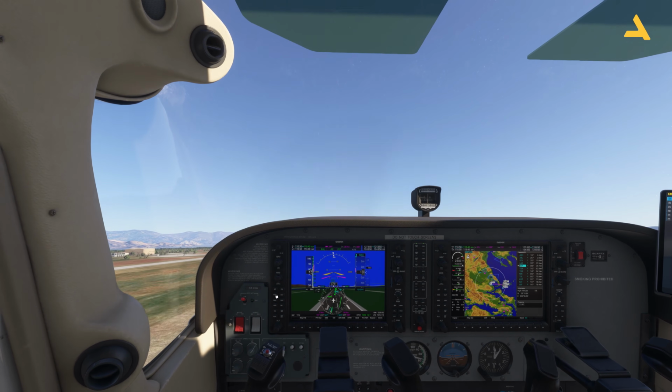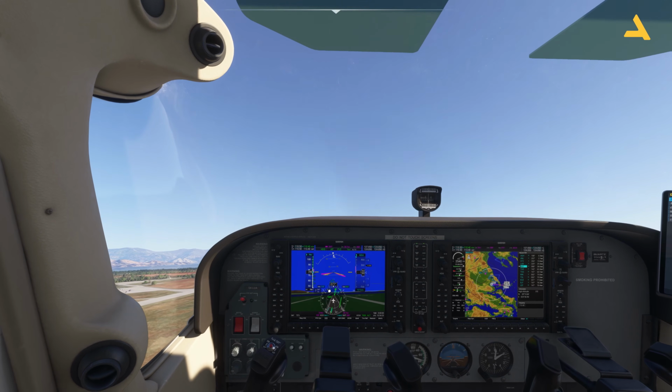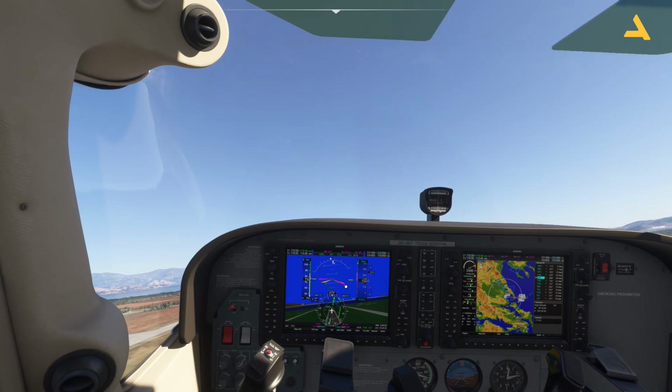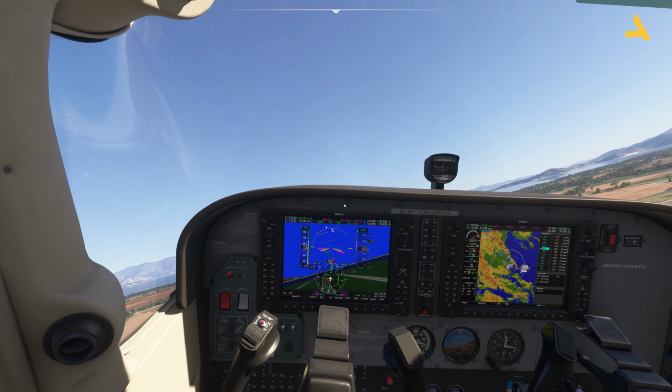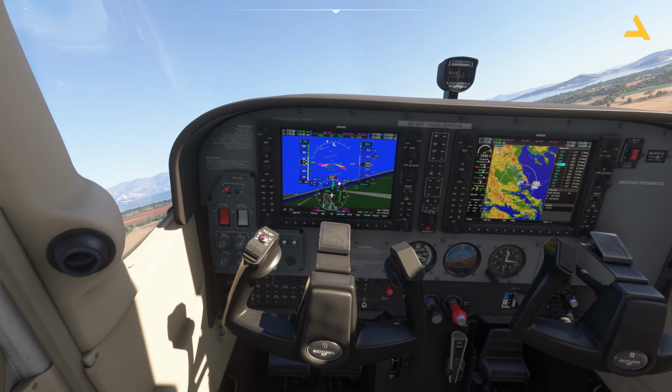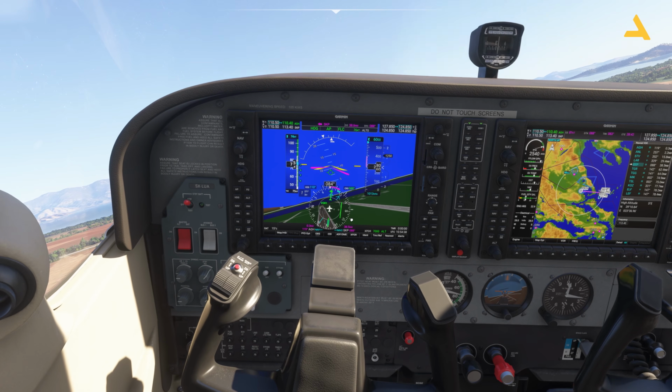And I can turn on the autopilot, heading mode, and flight level change. That's it. Now the plane will actually fly towards this VOR. Now I'm just going to pause it and just want to bring your attention to this bearing pointer. As now I'm crossing this VOR, you will see that this bearing pointer with a single line, it's changing. So soon it will be just pointing in this direction. You will know that you're going away from this VOR, which is AGH. And this distance will keep on increasing, and this distance will keep on decreasing.